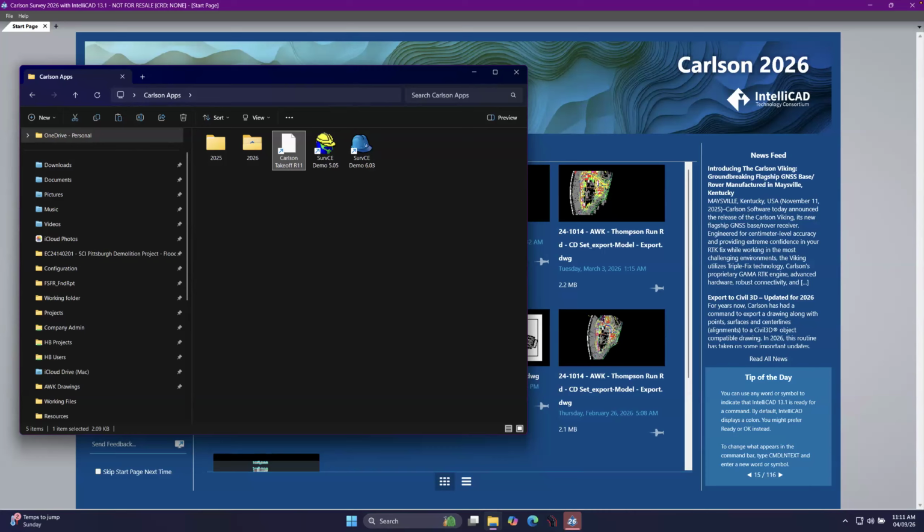Once you have a finished grade surface, you can go into this command called triangulation file utilities, and then you can subtract from that surface. Give it the dial down amount, and it will create another surface for you that is the finished grade less your subgrade materials, down to your subgrades. If it happens to be a uniform depth, you can take that manipulation as well.